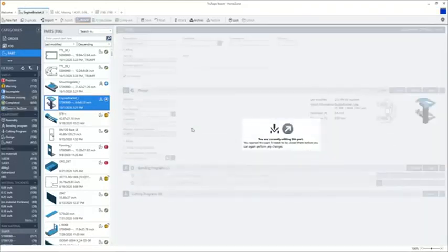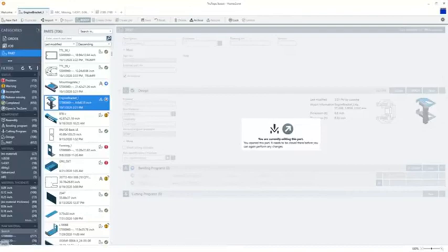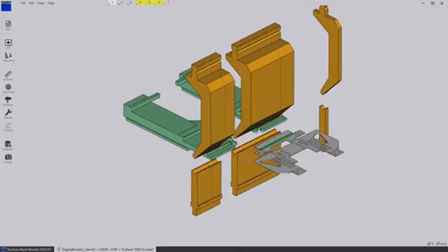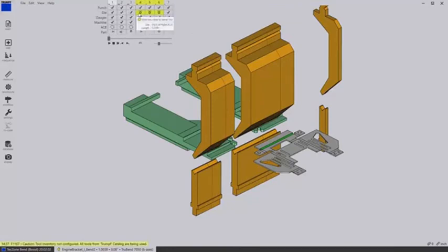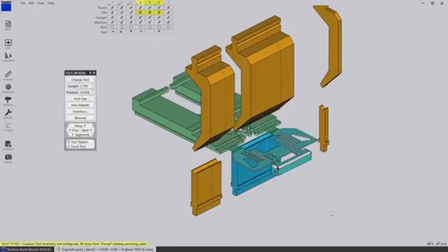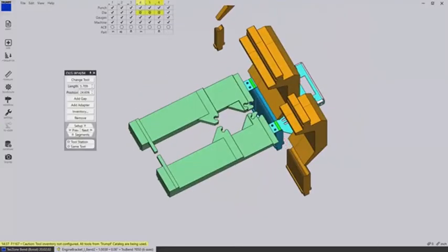So I'm going to open up the program in the text zone bend area. So you saw the text zone for the cutting. Now I'm going to show you the text zone for the bending. Okay, so here's our text zone bend. Here I can see the bend sequence and any issues. So I can see mostly everything has check marks except for these 3 bends with the yellow warning. So let's click on them and I can rotate this and look around.